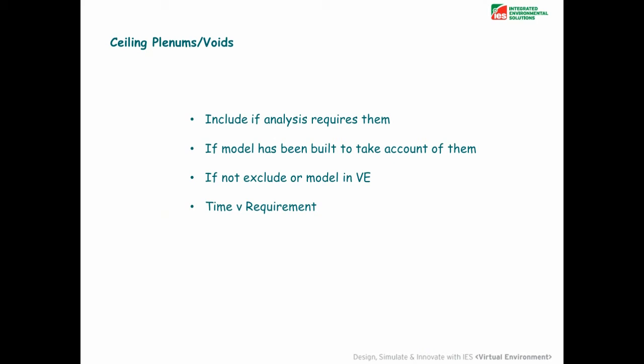Now I mentioned about ceilings, a small part about ceiling plenums and voids. As you look in plan view, you need to create, as I say, a space or a room into that void. But as you're going up through the building for a ceiling plenum, there's a number of ways that you can look at it depending on the complexity of the design. As I say, early stage, you're probably not going to have too much of an issue looking at that, but maybe if you're further on down the line and you start to look at energy analysis, you may have to consider other options to make it easier for yourself.